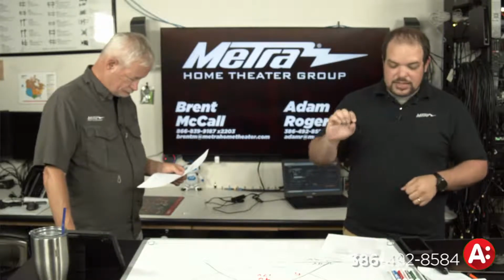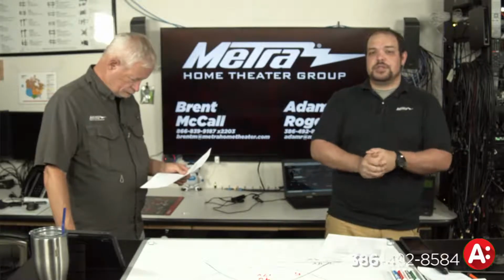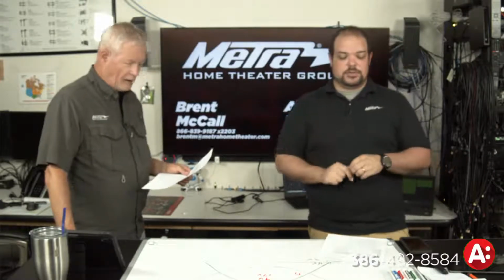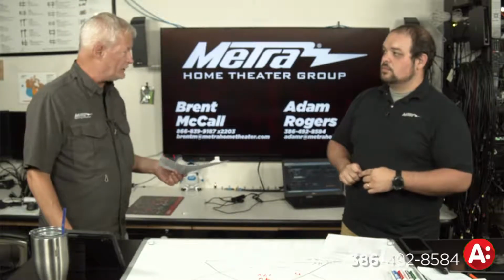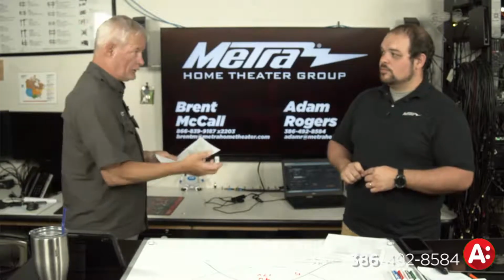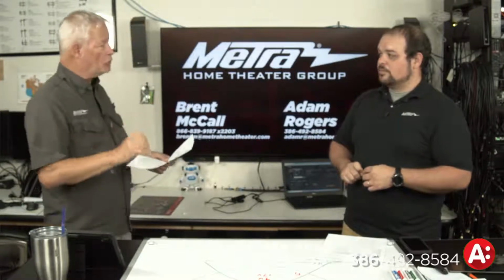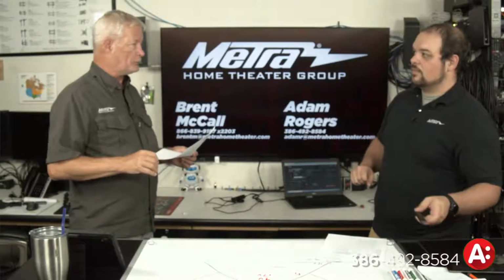So that's 802.3 AF. That's what all of our standard PoE cameras are using, not the PTZ cameras, and it's standard for access points, VoIP devices, things like that. As an industry standard, it has been around pretty much as long as there's been PoE, and it's still a good chunk of the products until we get to power-hungry devices.